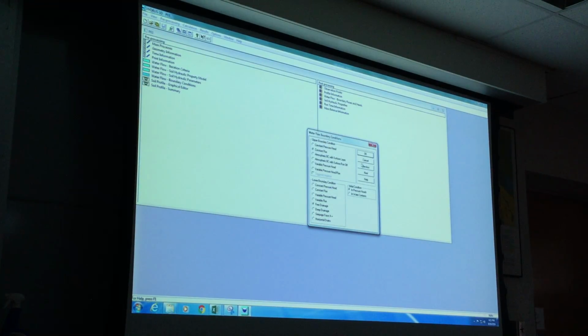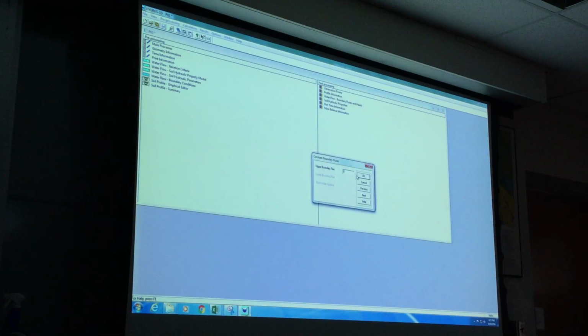So now I want to switch from a constant pressure head to a constant flux boundary condition. And then when we go to next, we actually need to specify the flux. And here we say it's equivalent to the saturated hydraulic conductivity. So we say 1.04 centimeters per hour. The only thing is, we need to be really careful, because this is a flux that is actually going into the soil profile. We need to give it a negative sign,